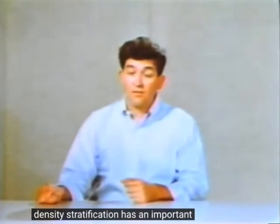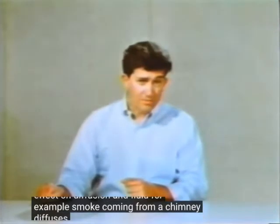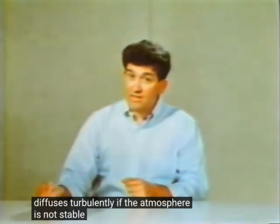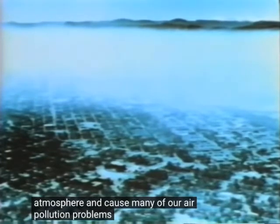Density stratification has an important effect on diffusion in fluids. For example, smoke coming from a chimney diffuses turbulently if the atmosphere is not stably stratified, as we see in these speeded up pictures. When the lower air is stable, as in the morning or the early evening, the smoke comes out and flattens into a long, thin layer. Strong stratifications, or inversions as they are sometimes called, confine contaminants to the lower layers of the atmosphere and cause many of our air pollution problems.